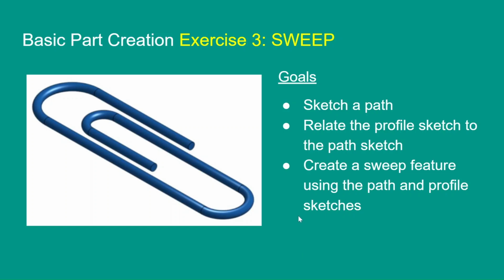Welcome. Our next activity is to create this paperclip, which will demonstrate the use of the sweep function. This is basic part creation exercise 3, sweep. We're going to sketch a path, then relate the profile sketch to the path sketch, and then sweep a feature using the path and profile sketches.